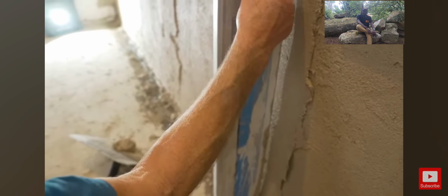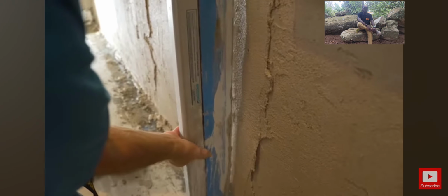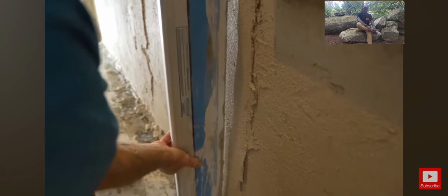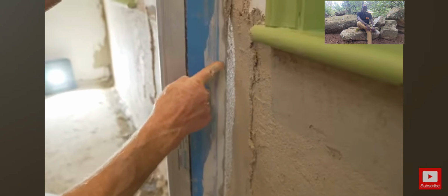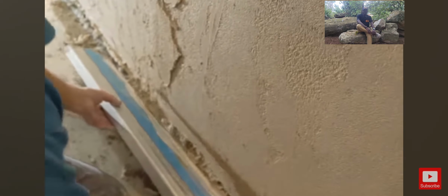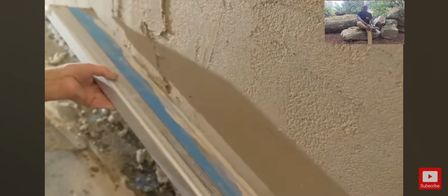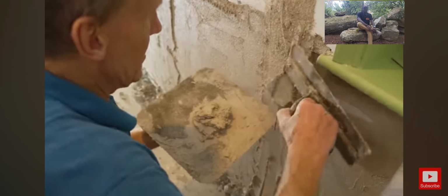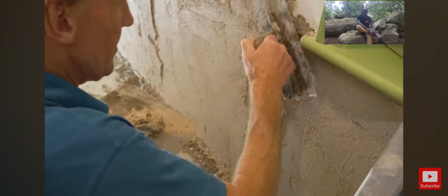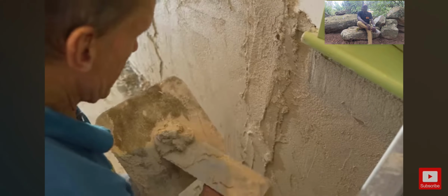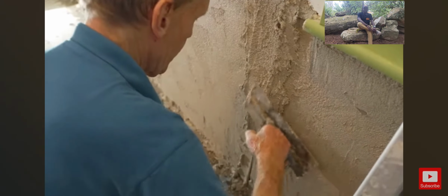So you can see the light coming through here. That's why I put that light on the wall down there. So you can see where the hollow spot is. So I just need to put a bit more in there. Then when I've got a few of these bands or screens down the wall, if you like, then all I'll be able to do is go up and straighten the wall out all the way along so that it's the same as the top. Put a bit more on there. A bit more on there.